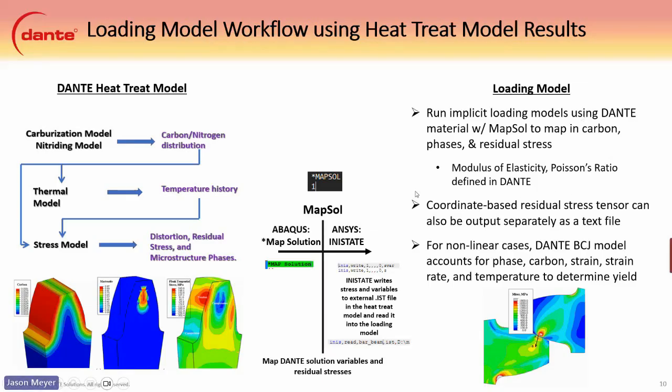Another way you can do this is through a coordinate-based residual stress tensor. So you can map out that stress tensor and then bring that into your loading model, but you do lose out on the advantages of Dante here with the carbon and phases and things like that.